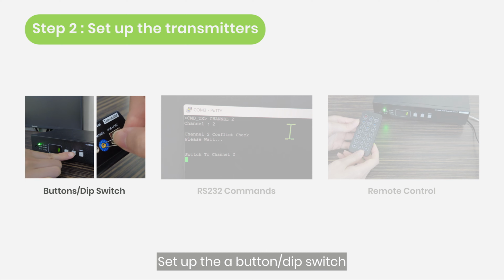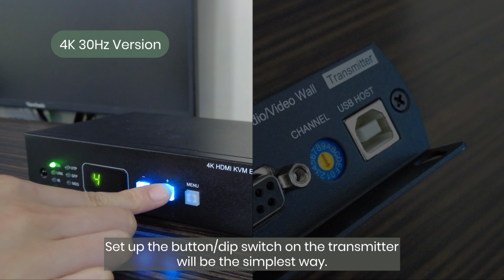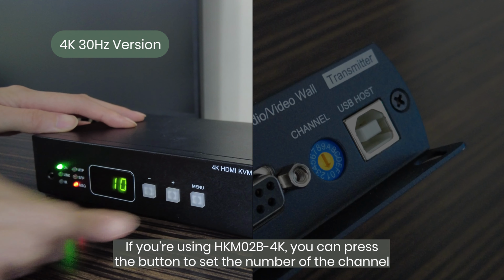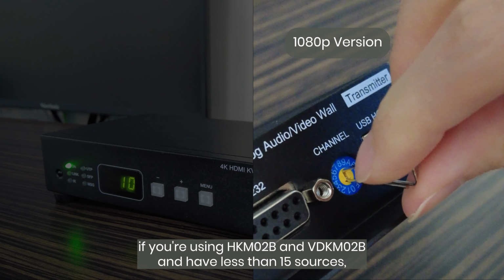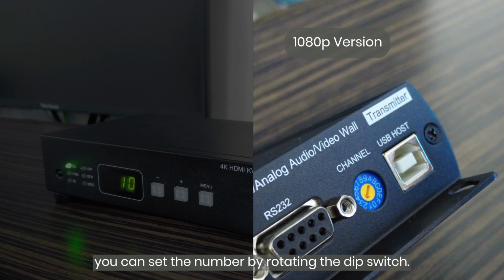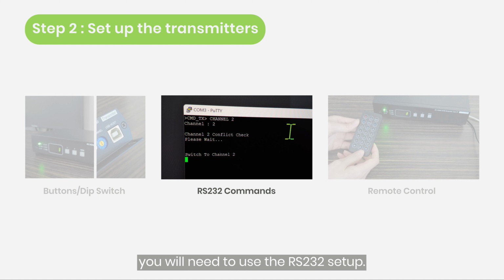Set up via button/dip switch. Set up via the button/dip switch on the transmitter will be the simplest way. If you're using HKM02B 4K, you can press the button to set the number of the channel. If you're using HKM02B and VDKM02B and have less than 15 sources, you can set the number by rotating the dip switch. For more than 15 sources, HKM02B and VDKM02B, you will need to use the RS-232 setup.